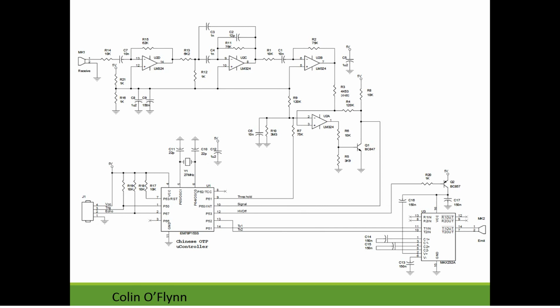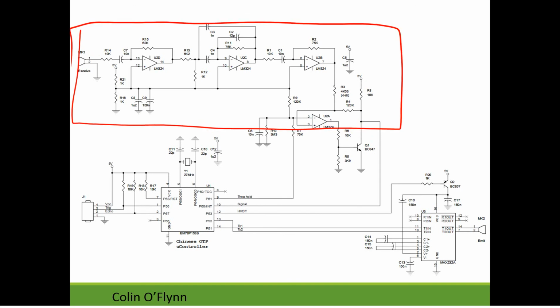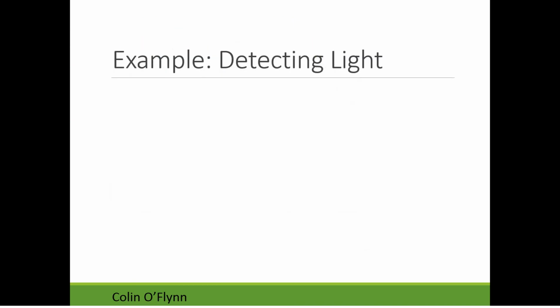And it does this with just RC filters. So sections of this input here are doing the filtering as well as the detection of the final signal. So we'll very briefly show you how to design these filters such that you can use them in your robot for performing frequency selective work.